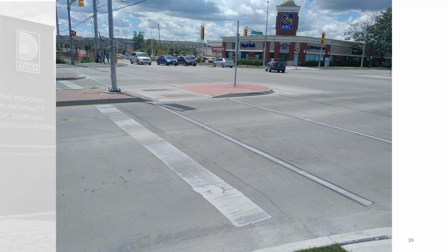So here's probably the biggest issue, and this is something that in hindsight we should probably have done differently. So here's a maintenance hole, a storm maintenance hole, and it was buried under the existing asphalt. So we didn't know it was there. We actually thought it was in the island, according to our as-builts from previous years. But when they peeled off the asphalt to do this project, they found this old storm maintenance hole. So we raised it to grade because we figured that was the right thing to do. And then they built an isolation joint around it, and we paved it just like any other manhole.